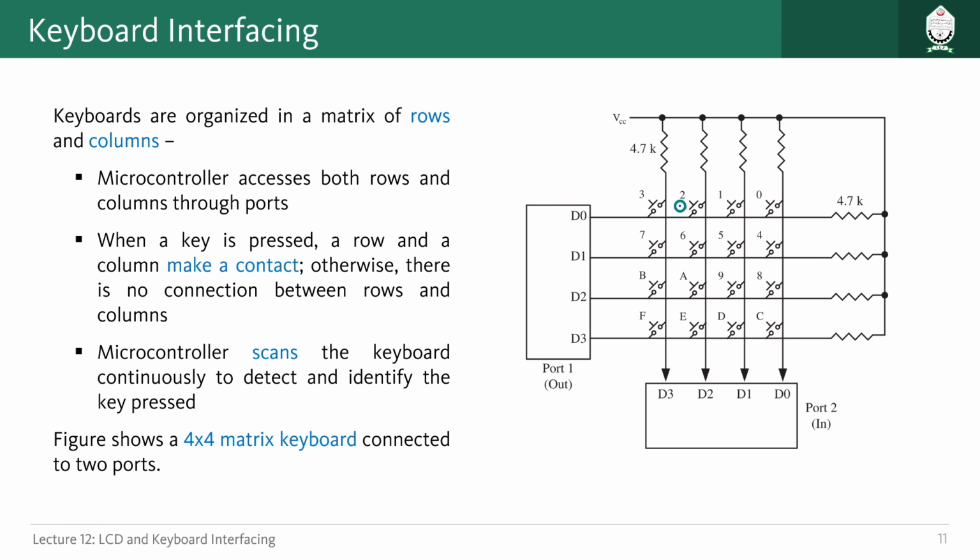So in one of the ends they are connected with supply voltage. The other ends will be connected with microcontroller. So these 4 rows and these 4 columns will be connected with microcontroller pins, and because of that the microcontroller will understand which particular button has been pressed.